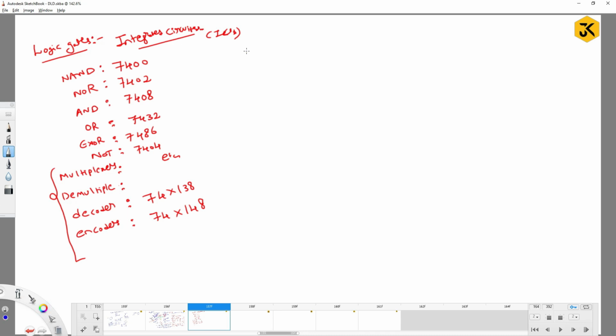For example, we have seen a concept called conversion of octal to binary, using encoders, not decoders, right? So what is the meaning of this? If I give 8 inputs, I need to produce 3 outputs, right? For that, we drew a truth table and constructed a circuit diagram, and then it works as per our requirement.